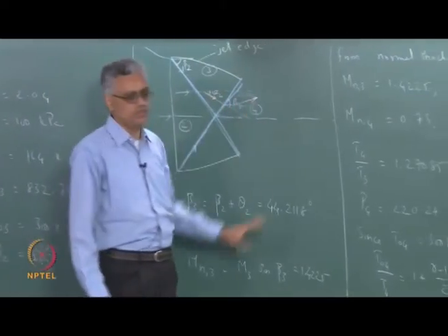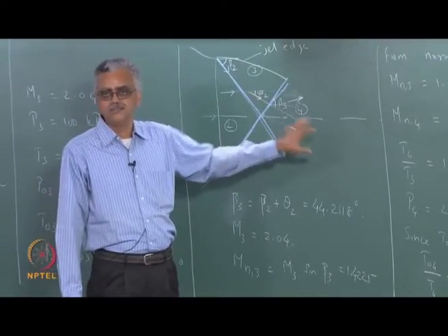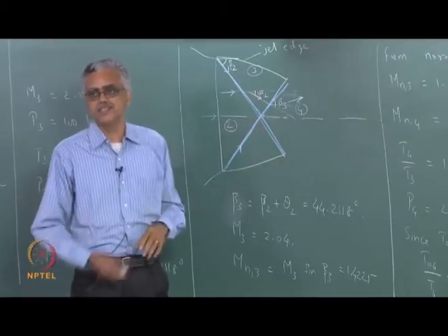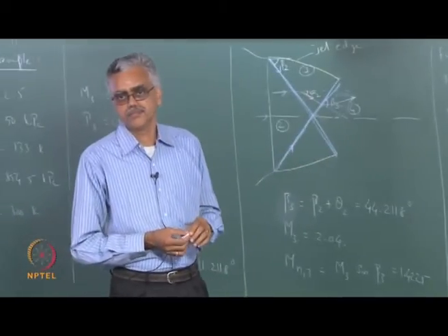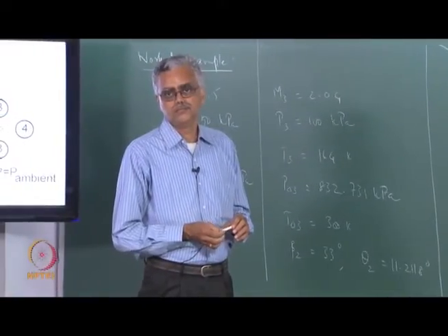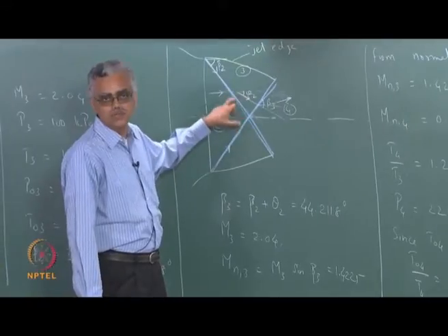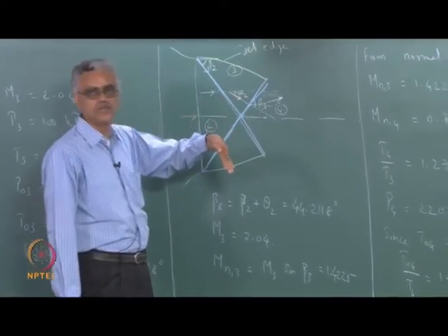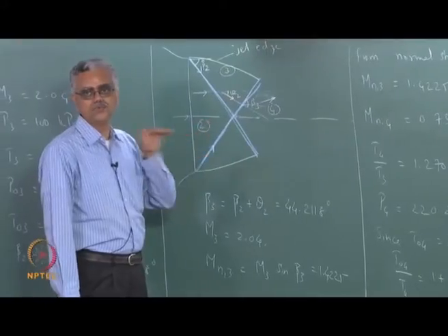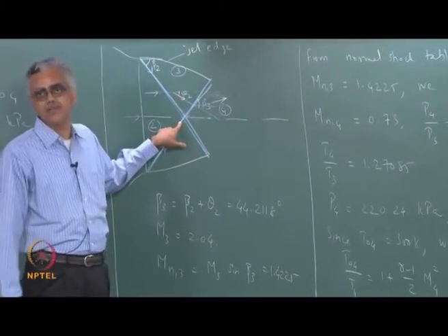And if you actually do a full two-dimensional calculation, you will notice that the results you get are almost identical to what this simple theory predicts. Yeah. Flow through the center line. Actually, there cannot be any flow deflection. Correct. So that means what's happening is, within the framework of this theory, if you go through the center line, this shock wave is trying to deflect the flow this way. The other one tries to deflect the flow this way, so that it goes through without any problem. But what can happen in some of these situations is, this interaction is a little bit complicated.